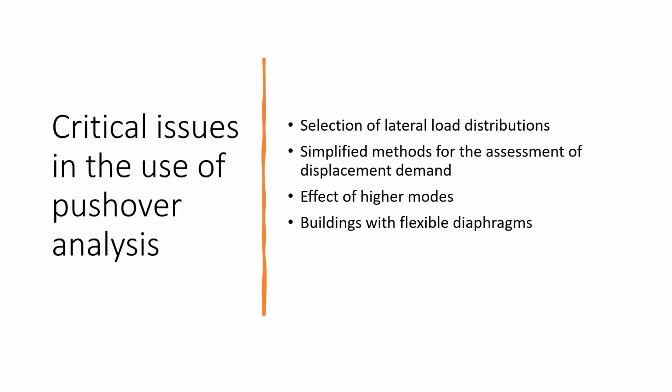Another aspect that needs to be considered is the effect of higher modes, and what is typically done is that the pushover response is somehow corrected by applying some coefficients, some forces that derive from the linear response to higher modes.